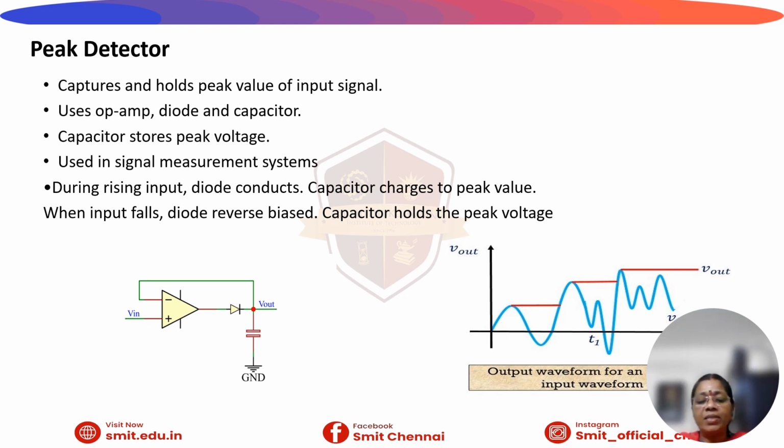Hence, to overcome this limitation, we have to use a high switching MOSFET, which should be connected in parallel with the capacitor. Higher precision designs may include a second diode in the feedback loop to prevent the first op-amp from saturating negatively, which speeds up the recovery time for detecting subsequent peaks without missing any peak.